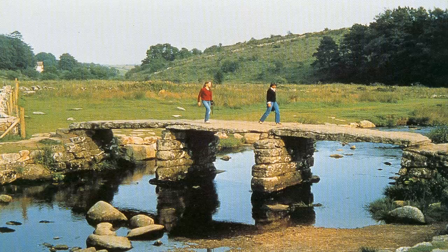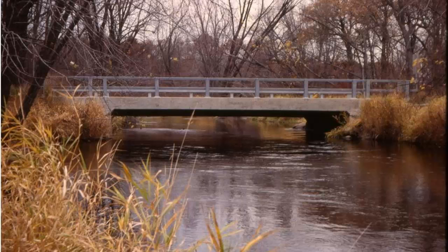The most basic structural system might be just a single span beam system on simple supports to hold it up. This bridge over the McCann River is just a large slab of concrete. The entire slab is like a beam spanning over the river. At the ends, the slab just sits on the abutment walls.